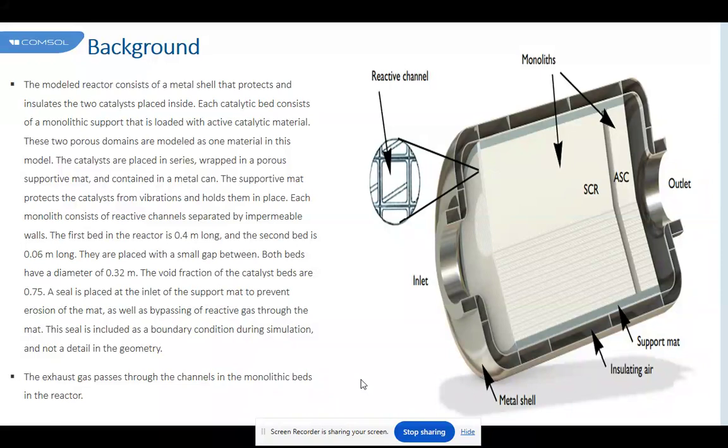However, there was still a marked preference of the flow for passing through the monolith that imposes the lowest viscous resistance despite its location. Regarding back pressure, this simulation shows its sensitivity to the size of the core. The relationship between the variables is slightly nonlinear. It is somehow striking that the two cases with the evenly distributed flow areas led to an almost identical pressure drop regardless of the placement of the monolith with the highest and lowest cell density, core or ring.